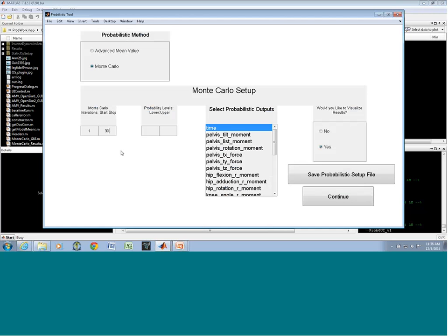But let's say I've run 30, but I figured out that I need more for it to converge, or I want to assess if more simulations will provide a better result, I can then go and run from 31 on, is the point there. And then the probabilities, we can look at any probability levels that we want. It's set here to look at 2, and so we have been talking about the 5 and 95% confidence bounds.